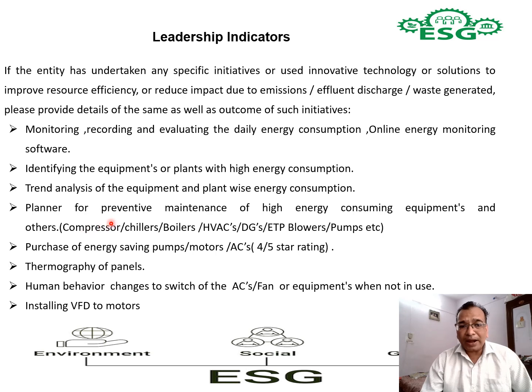Then you can make a planner for preventive maintenance of high energy consuming equipments and others. Once you know which are the equipments or the plants with very high energy consumption, then we can focus on them and plan preventive maintenance drives, particularly for the compressors, chillers, boilers, HVAC system, DGs, and other blowers, high HP blowers, pumps. This will definitely give you an edge to reduce the energy consumption or to maintain the energy consumption.